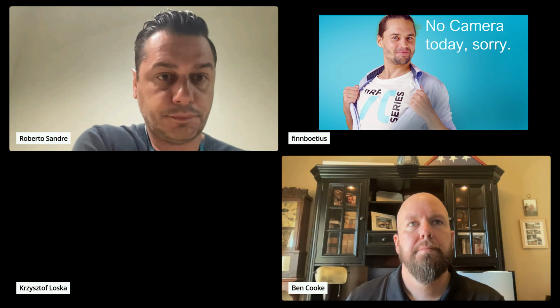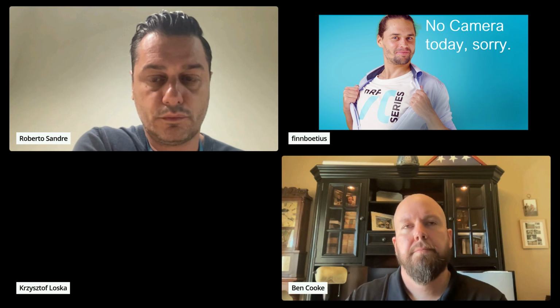Okay, then this one is probably for Christoph, I think. So can I do Amazon Sidewalk development on my Thingy 53? So what we natively support in nRF Connect SDK version 2.5 is DKs for nRF52840 and nRF5340. But we also provide device tree definitions for Thingy within the SDK. So I believe you should be able to quite easily transform the existing sample for 5340 DK into the Thingy.